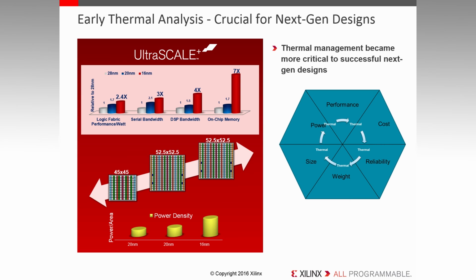All these factors have forced chip manufacturers to employ techniques to control the die temperature. It's very important to consider and deal with thermal challenges early in the design cycle. Xilinx Power Estimator has capabilities to allow customers to better understand and track FPGA junction temperature throughout the design process, to ensure junction temperature does not become an issue late in the design cycle. Let's look at it in detail.